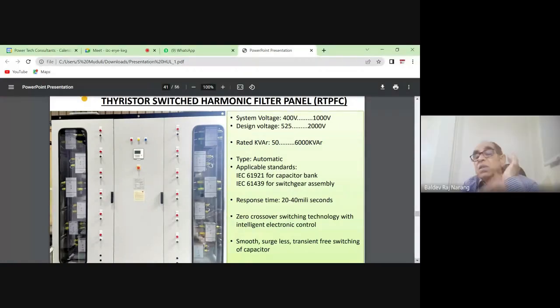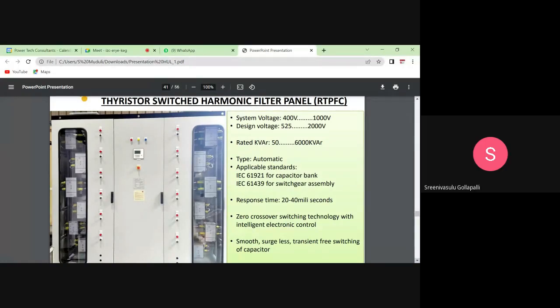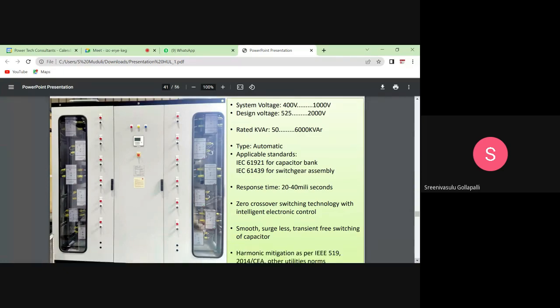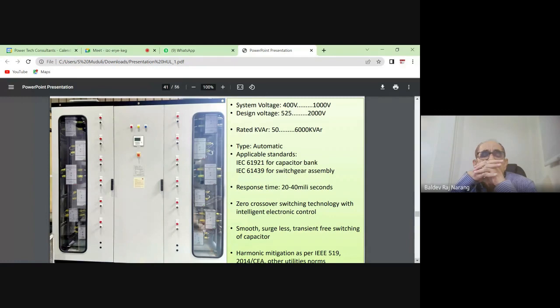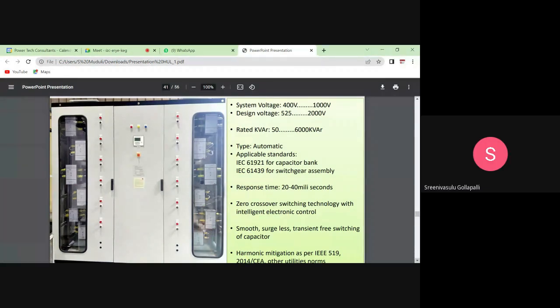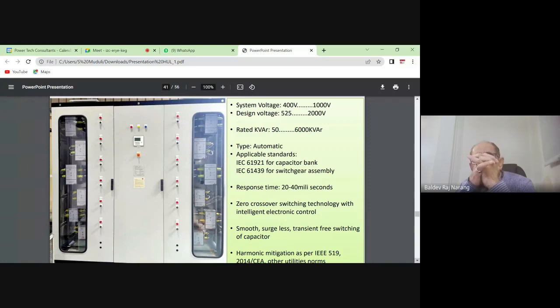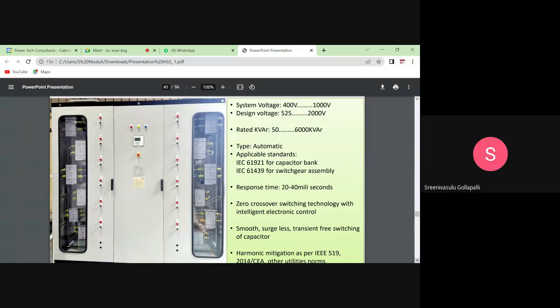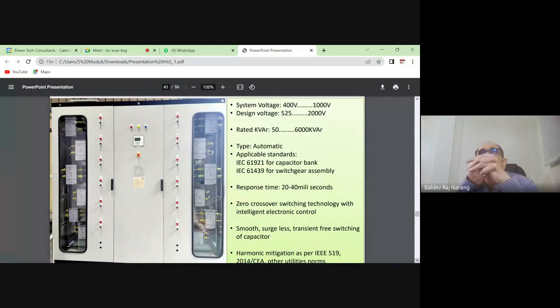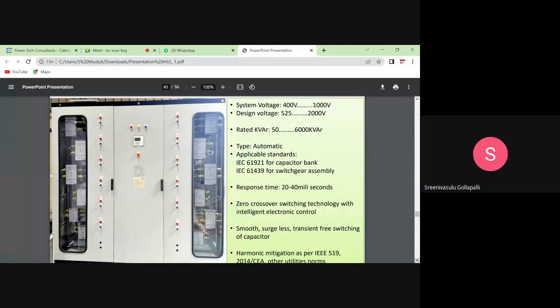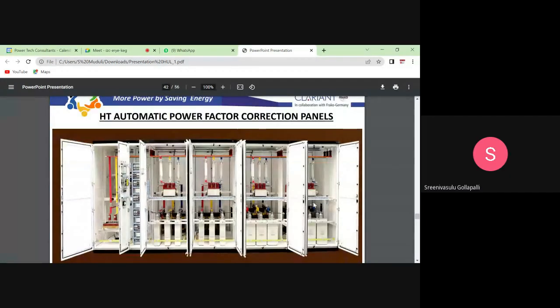Sir, I have one doubt. Suppose you are operating on medium voltage soft starters, for example 3.3 kV, 6.6 kV. For those soft starters, the firing angle is decided by the customer only. Correct. So at that time, the voltage magnitude that is selected, the remaining portion is going to be a waste of energy. That waste of energy will convert into a form of nonlinear distortion. Correct. So how is that going to be handled? It's a kind of harmonic. Yes, for a certain period, for example 1 minute, 2 minutes.